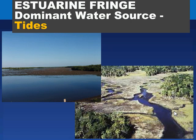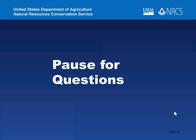We actually have channels that are in equilibrium with the volume of tide, which, by the way, is referred to as the tidal prism, and the flow energy and whatever sediment sources are coming in. So the equilibrium in these tidal inlet channels is very similar to a stream channel equilibrium. And the tidal inlet channels also are very analogous to channels referred to as bayous in the lower Mississippi Valley, where water moves back and forth in the channel between the stream and the adjacent landscape.